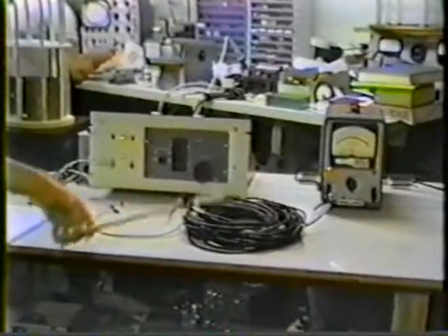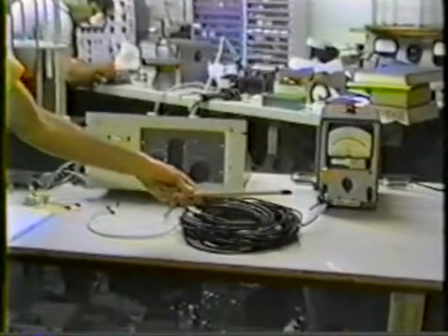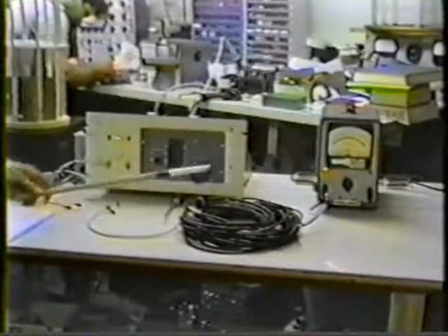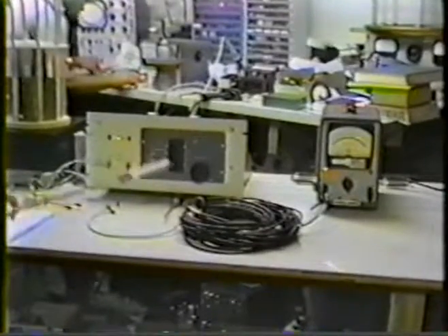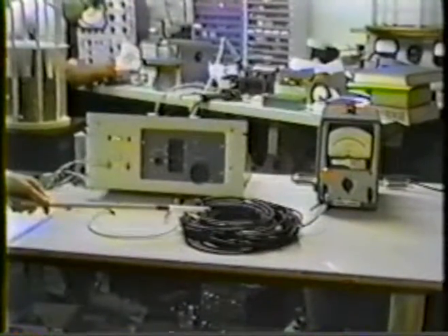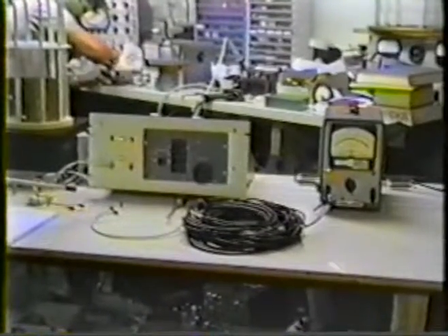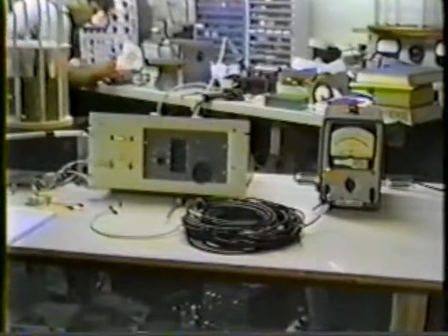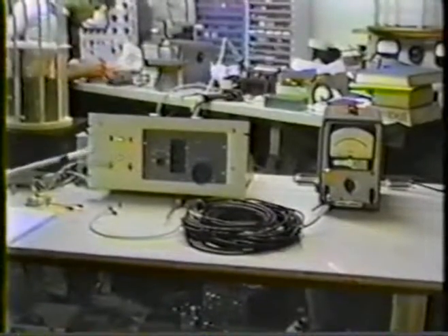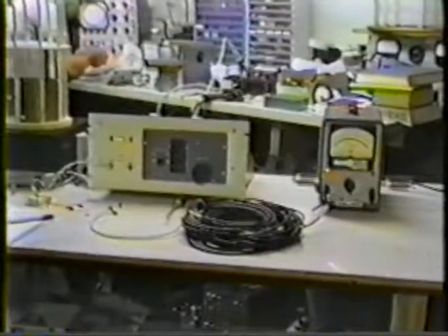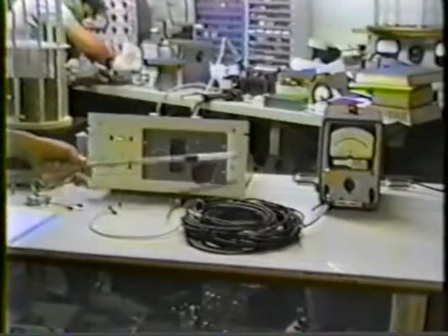These impulses will travel around in the cable, reach the open circuit at the end of the cable, turn upside down, and reflect back, and again be delayed and return to the oscillator. When the impulses of the oscillator frequency are such that they match the time of propagation delay produced by the propagation of electricity down the cable, when this inverted impulse comes back from reflection, the oscillator has gone through 1/2 of a cycle, and it also is producing an inverted impulse. So these two inverted impulses add, and a double impulse goes back down the cable, turns right side up when it gets reflected, comes back to the oscillator.